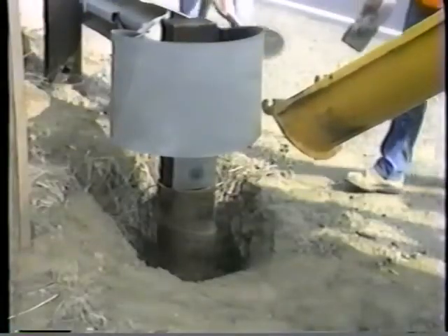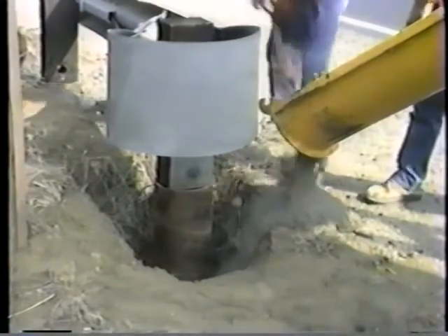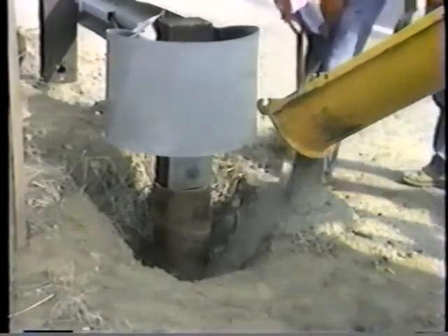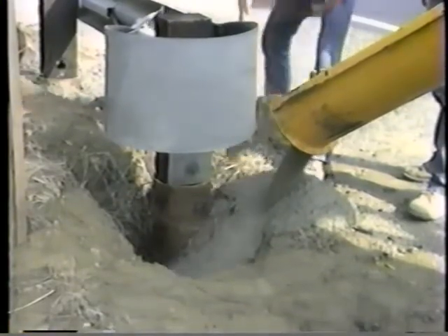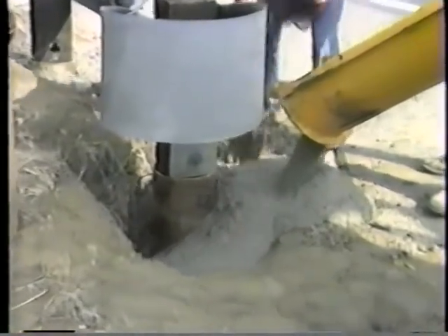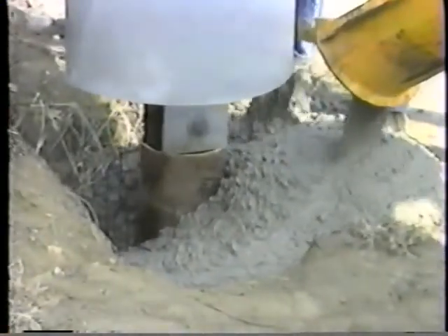To ensure that the first and second posts of the system break away and are not pushed over when impacted, they're set in concrete footings of at least 3-foot depth. The surrounding soil must be stable. A loose sand will not work.